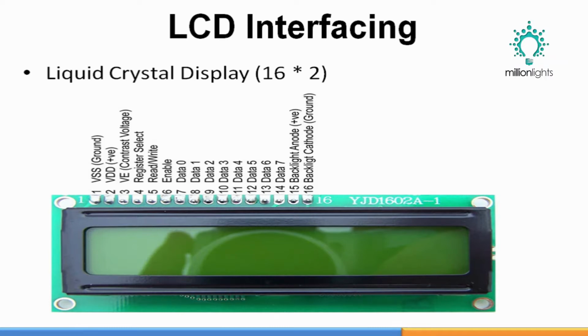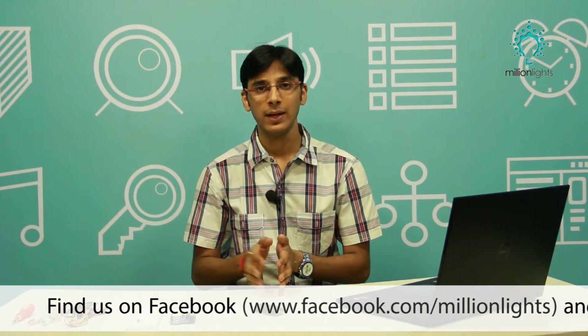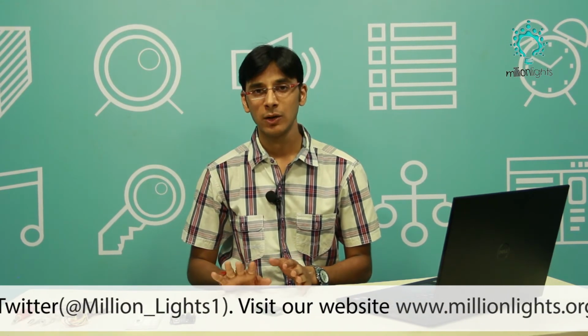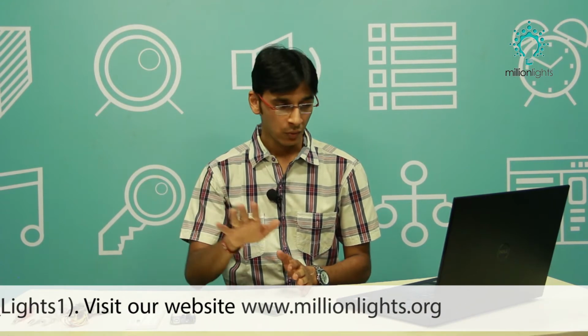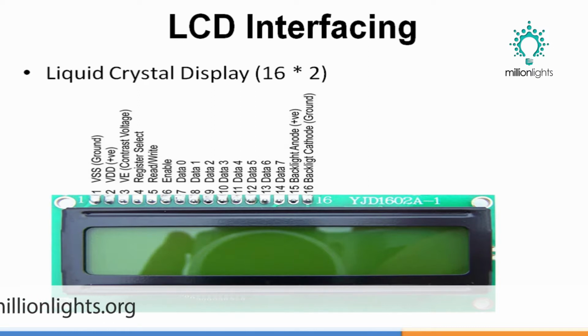Then from pin number 7 to pin number 14, that is data 0 to data 7. These 8 pins are connected to your Arduino for transmitting data. The data is a character. One character means 8 bits, because we have an 8-bit ASCII code for each and every character, symbol, number. Everything is in ASCII. Therefore we require 8 bits to be connected from Arduino to this. These are pin number 7 to pin number 14.